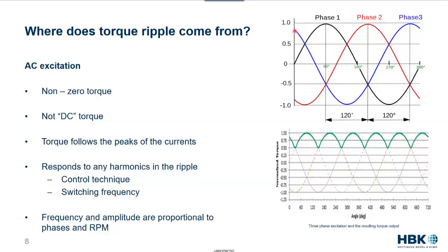And the torque is going to follow whatever the maximum of the torque is at any given time. So you can see that in this bottom graph, we've just put a green trace following the maximum of the instantaneous current, and that's what the torque is, and that's where the torque ripple comes from. So you can clearly see the AC nature. The average torque value is going to fall right in the middle, but it's really got that transient